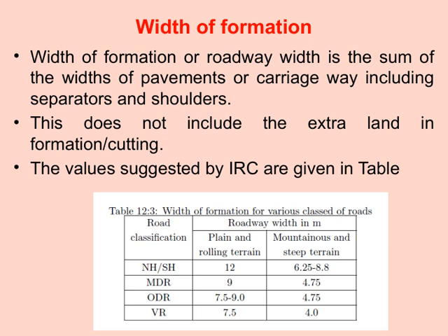Today, we're going to focus on the width of formation, which is a critical aspect of roadway design. The width of formation, or roadway width, refers to the total measurement across the paved surfaces. This includes the widths of pavements or carriageways, as well as separators and shoulders. It's important to note that this measurement does not account for any extra land used in formation or cutting. Essentially, we're talking about the actual paved area dedicated to traffic movement.